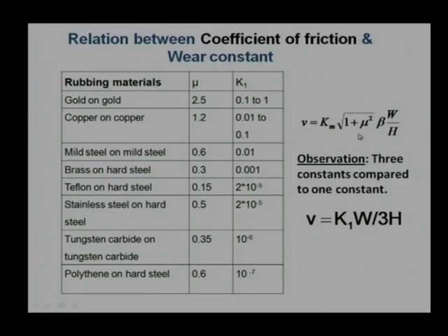If I have to do experiments, this equation will be preferred because there is only one wear constant, so I require a lesser number of experiments. However, Rowe has supported that with the lubricant layer things will change. The Archard equation can also be interpreted in a similar manner. We say that if there is more and more lubricant layer, K1 will keep on decreasing. So, there is not much problem for us.